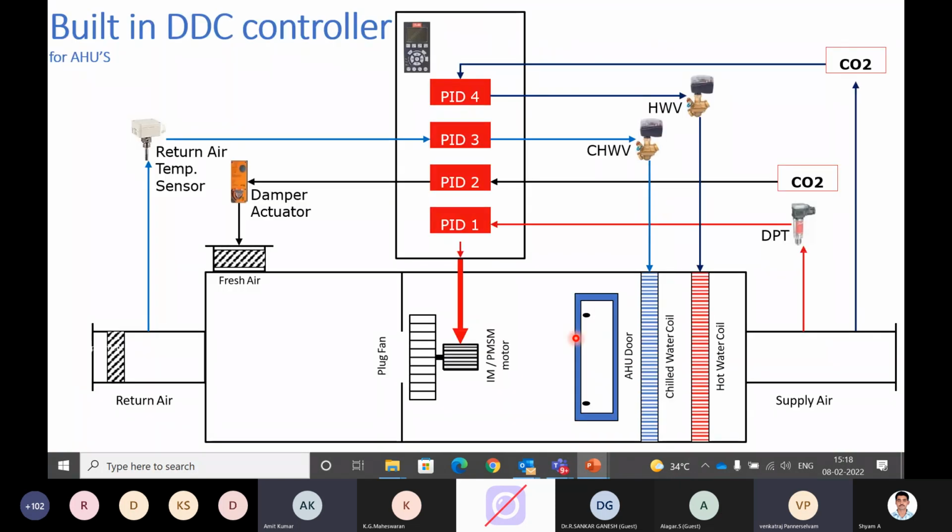Okay, so this VFD can also be used as a standalone device for any of your critical applications. Suppose you are using it in complex applications of pharma or industry applications, this VFD has inbuilt PID loops, meaning that there are 4 PID loops. By using these PID loops, we can control any of the external HVAC devices or industrial application devices through the VFD.